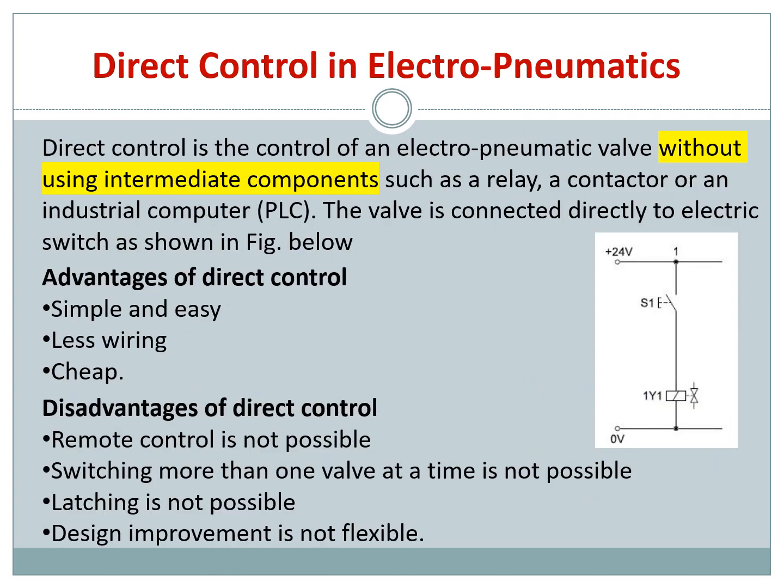Okay, so as we saw just now, we have two ways of control. It can be direct control or indirect control. So first we look at direct control. Direct control in electropneumatics is similar to pneumatics. Okay, so your switch is connected directly to the solenoid. One solenoid is connected to the actuator. So when you press this switch, this solenoid will be activated, and your cylinder will extend.